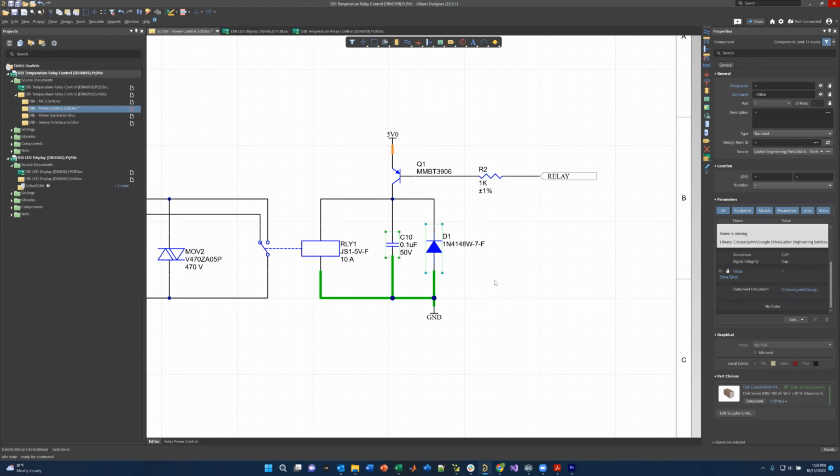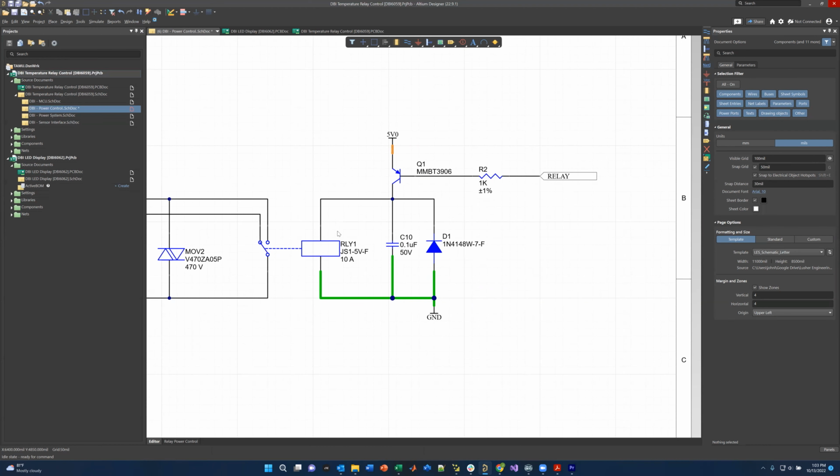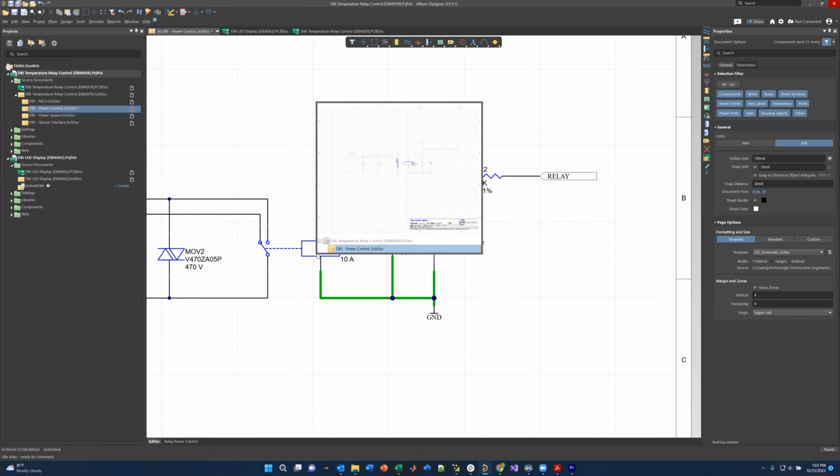This is for preventing spikes from reoccurring on your main power lines. So we've got an inductor basically here. It's a coil of wire. And when that coil is energized, it has a magnetic field. When it's de-energized, that magnetic field wants to still be present.